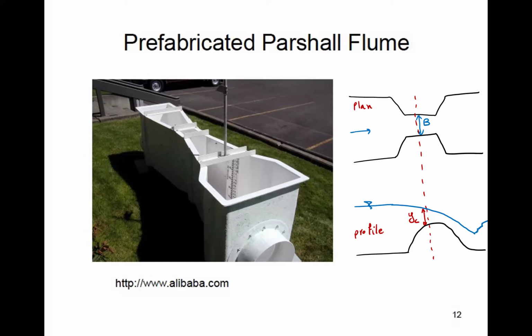But again, that's a combination of lateral constriction and blockage along the bed, a hump or something similar to a hump. Okay, so these are under the category of overflow structures, and all of them work based on the same principle. They choke the flow, create a critical hydraulic control, and then you use it for whatever you want, measure flow or control upstream water level and so on.